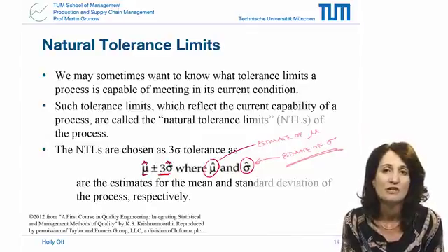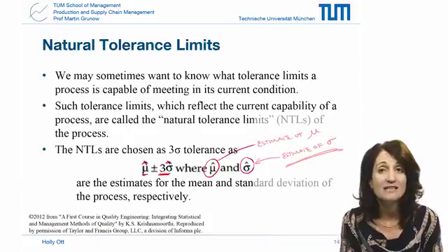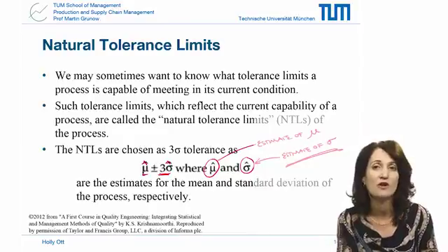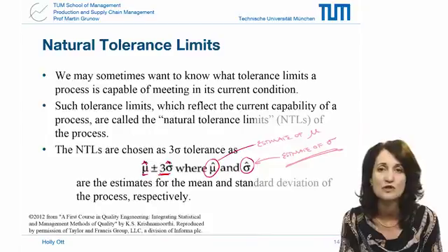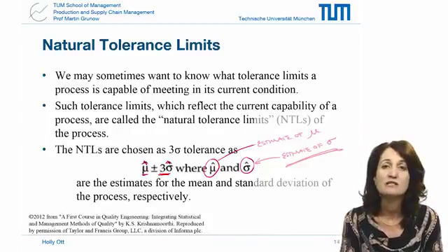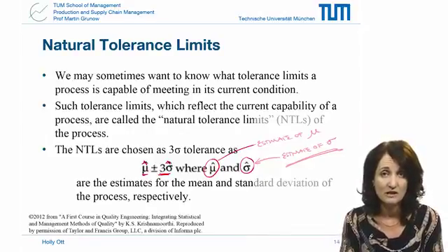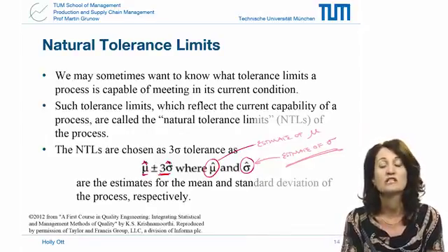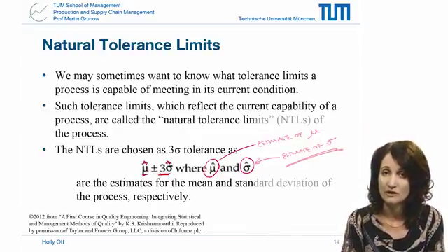So for an example, maybe you are making tires, and you have different rubber sheets that are used for layering the tire. And so this is an important variable. The thickness of these sheets is an important variable in the tire production, and you need to have a uniform thickness over all the sheets, and you need to make sure this is consistent to produce quality tires. The customer, though, is not interested at all in knowing the target for those sheets or the tolerance for the sheets. They're interested in the final overall thickness of the tire and the overall quality of the tire.